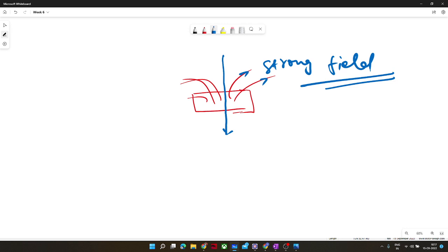losses, and the permanent magnet also has a temperature issue. If the current increases, the temperature will also increase, and that will demagnetize the magnet. And once a permanent magnet demagnetizes, it is very difficult to restore. So that's the first purpose. And the second purpose: rare earth permanent magnet extraction produces so many minerals, like a very high amount of minerals.